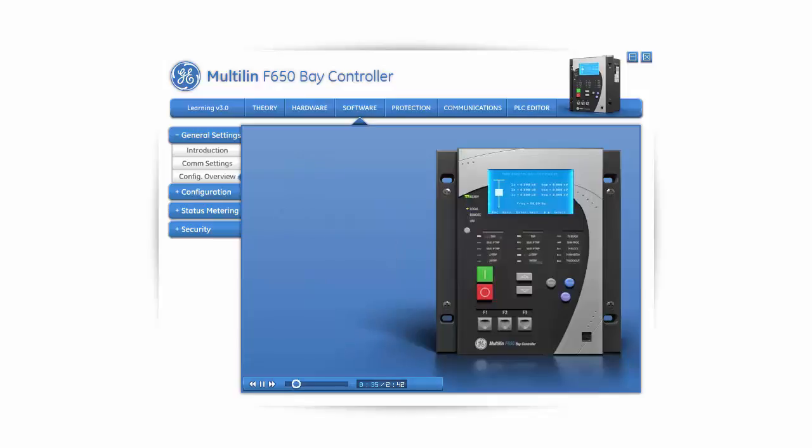Protection elements contains all the protection functions of the three setting groups. Whether a phase time over current element or a voltage element has to be configured, it can be found under protection elements. The control elements are the relay functions that are not protection functions but are auxiliary to protection relays and often found together with the protection elements inside the same device.